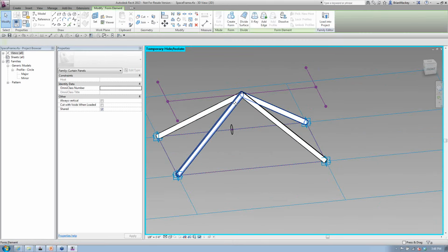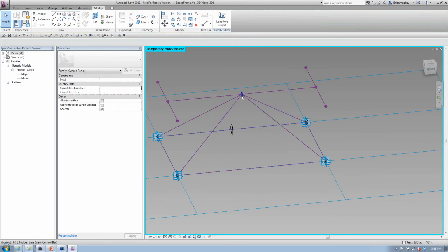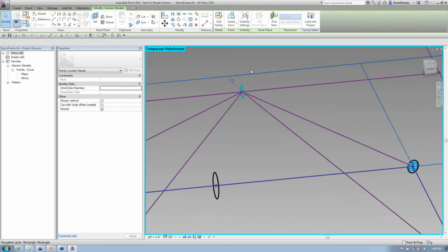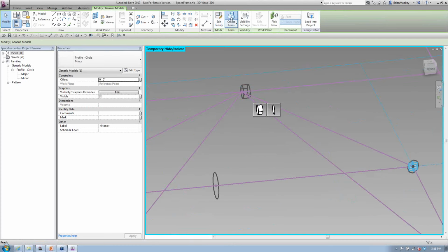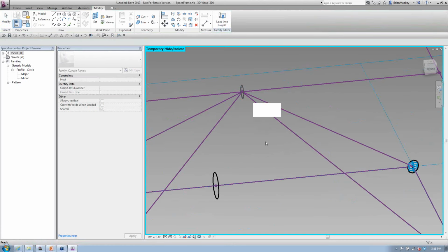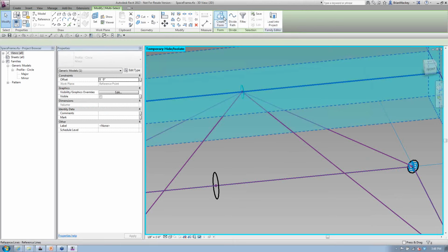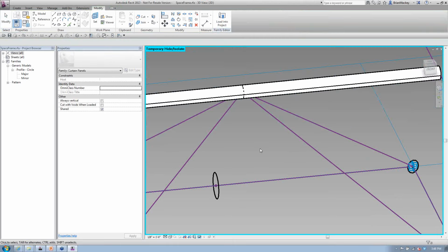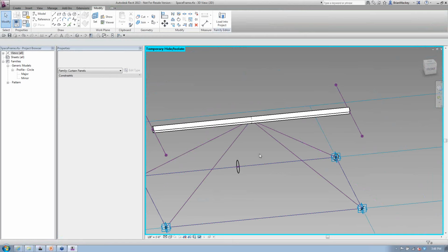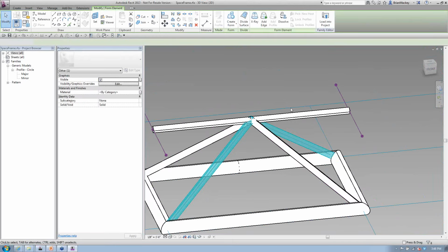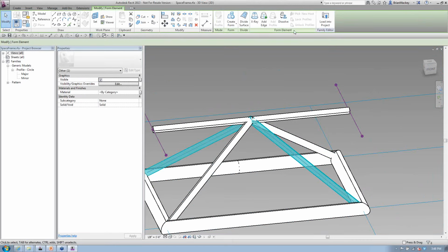And then, of course, my other circle's dead center. But there's one thing I want to show you here, and this gets me every time when I create the family. I forget to, oops, escape out. I forgot to grab the line. It gets me every time I start creating these families. If we look at the differences between this one, notice how when I grab this extrusion, the lock profiles or unlock profiles is grayed out.